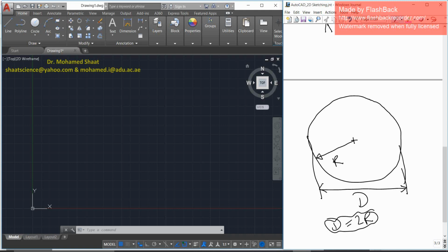Anyway, in terms of drawing by hand, you have to open the compass with the radius. So if you have the diameter, you have to divide it by 2 to find the radius, then you can draw the circle. But in terms of engineering drawing, which we will discuss in more detail when we practice how to add dimensions to a drawing that we just created, if you have an incomplete circle, like a small arc, it is better to specify the dimension of this arc using a radius.